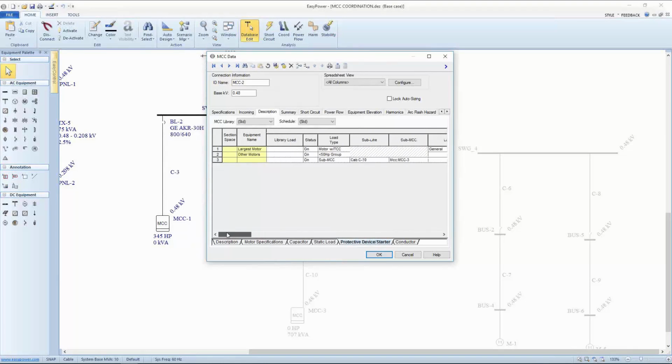Now, just because I'm here, I also wanted to talk about lumped motors. If you look at the IEEE instructions on how to regard motor contribution, they suggest that anything less than 50 horsepower is relatively minor contribution as far as fault loads, but if you have a large number of them, there could be some summation that would be worth considering. So the tool allows us to do that both for greater than 50 horsepower and less than 50 horsepower, and the difference there that will come into play is the X over R ratio.